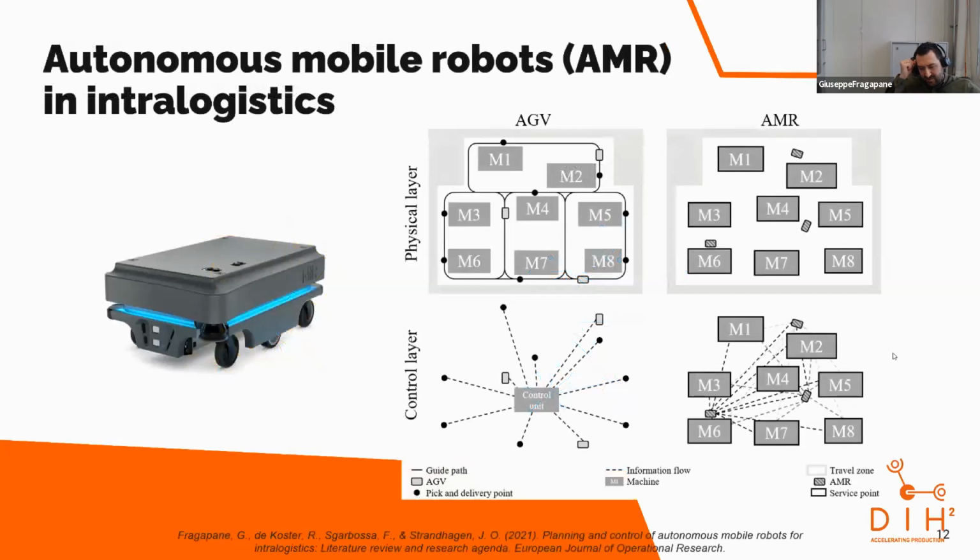With the AMRs, you decentralize the decision making towards the single AMR. It can communicate with the other systems to understand, and they are getting much smarter. The focus is to let all the AMRs talk with all the systems, let them understand where transportations or deliveries are needed, and they can negotiate. They negotiate with the other AMRs about which one should get a job, instead of one single control unit deciding it, and the one bidding the best gets it.